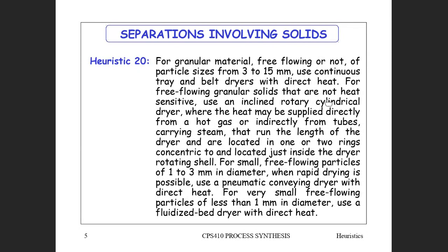But I reckon if you're using steam tubes inside the dryer, it's mechanically a little complicated, because the steam must rotate, so you've got to have a seal where the steam can enter.